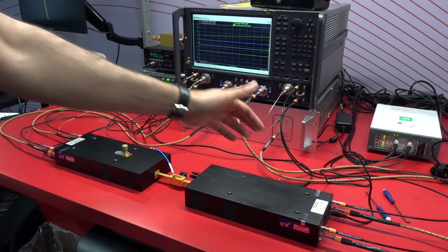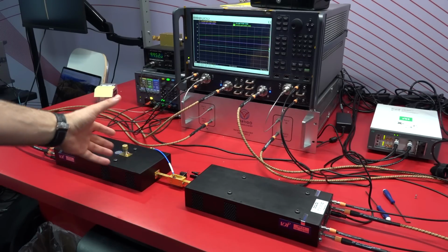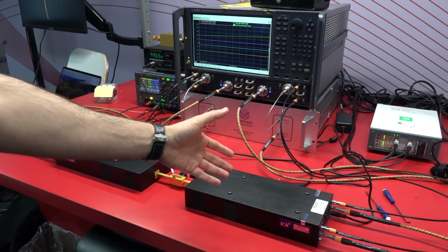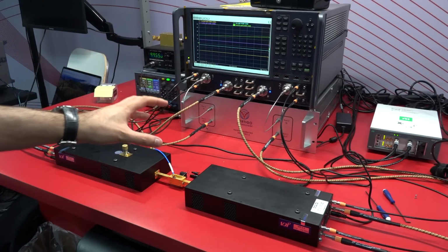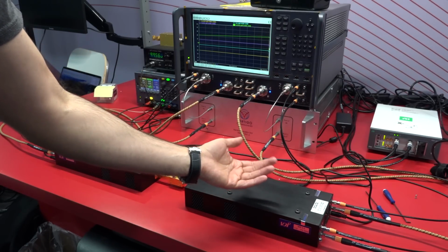So of course we know that from VDI you can get frequency extenders to almost any frequency. We saw now a 2 terahertz version, a prototype as well. So what you really want to do, if you own all the system, is find a way to do load pull using these extenders already with the equipment you have and with the PNX you have. So here what Maury is doing is controlling the phase and the amplitude of the signal that goes into the up converters.